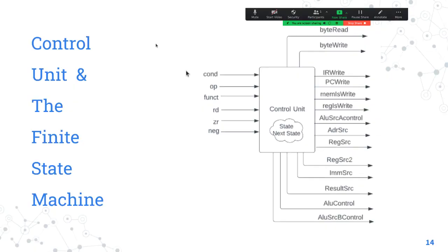So the control unit will have conditional logic. The opcode, function code, RD, these are from the IR. These are the different fields in the IR. Based on this and many other inputs, the different flags would be set. If you are currently in decode stage, the memory write, memory read, ALU, you will set all those flags to 0. They'll not work. They'll just be idle.